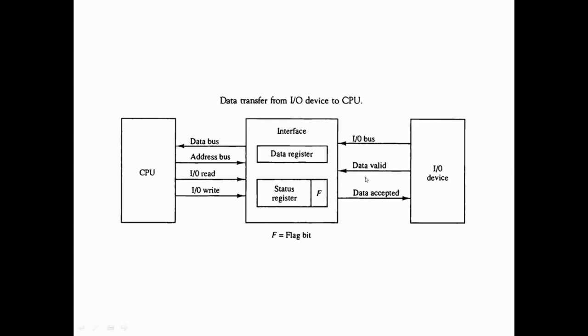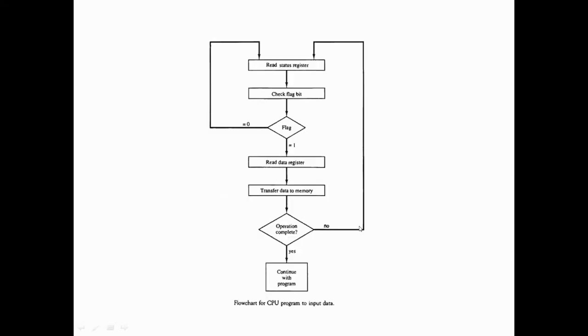So before transmission, every few nanoseconds or milliseconds, this register has to be taken here, and then an if operation has to be performed to check whether this bit is set or not. And only when this is set will the data from this data register be transferred here. Otherwise the CPU has to wait.